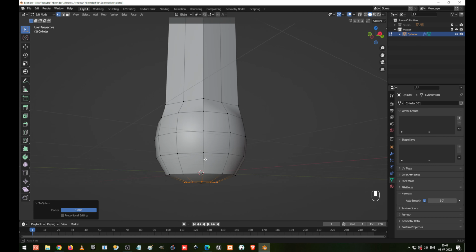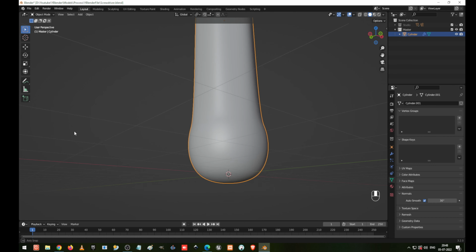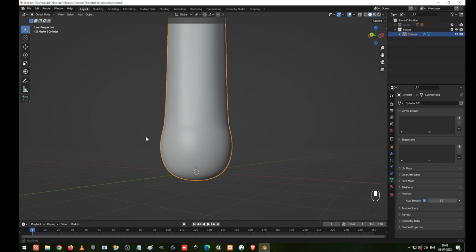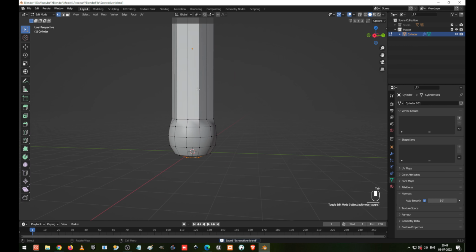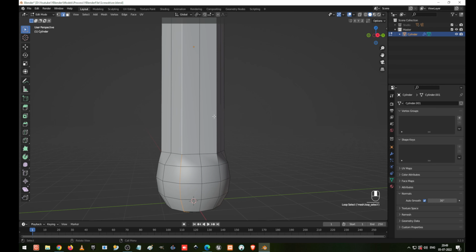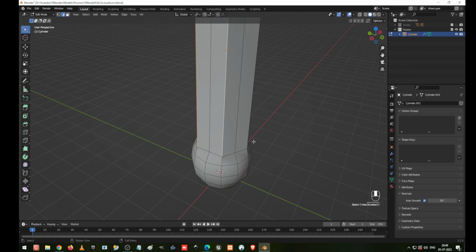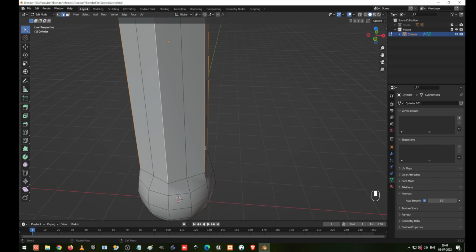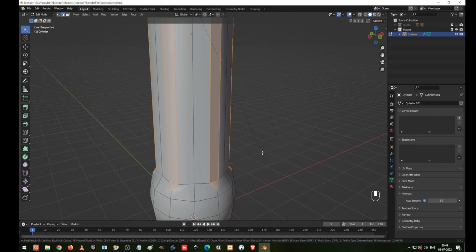So now I go to the object view. Now you can see it correctly, it has a round shape at the bottom. I save it once again, and I go to this edge and select these edges. Wherever the corner is, these 6 edges, I am going to create a bevel using Ctrl B and the bevel option.